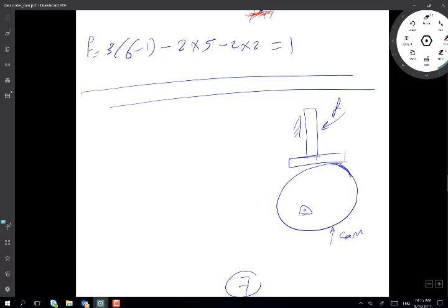The follower follows the motion of the cam. That's a linkage, right? And the contact here is an interesting contact I'm talking about. We know in this case, this here is the normal R, the revolute joint. This here is prismatic.